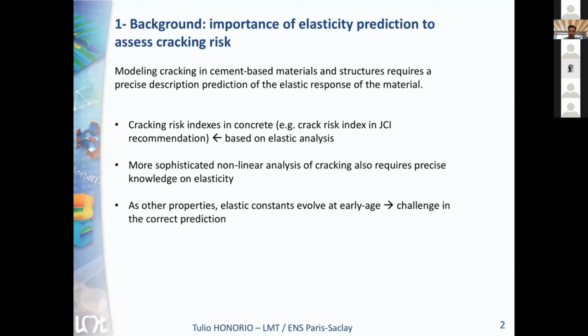if you want to assess the risk of cracking of cement-based materials. So if you use even simple approaches to determine the cracking risk, we need a good estimation of the elastic properties. If you use more sophisticated nonlinear analysis, you also need, as a main ingredient, the elastic behavior of the material.